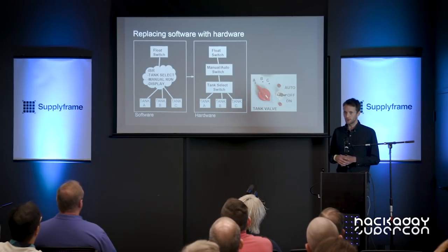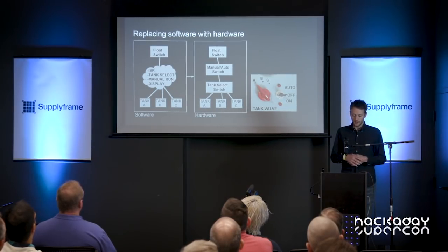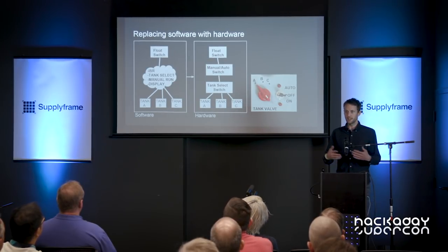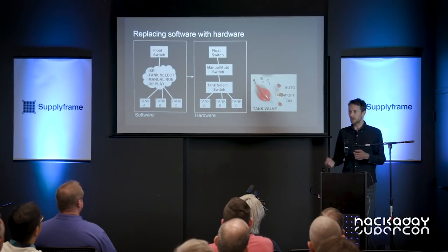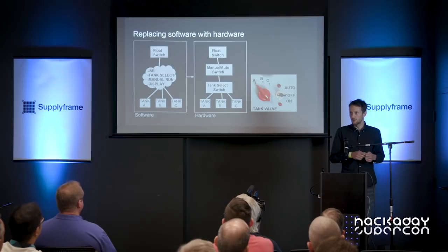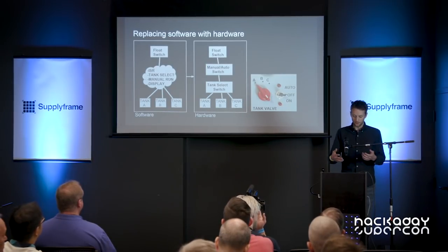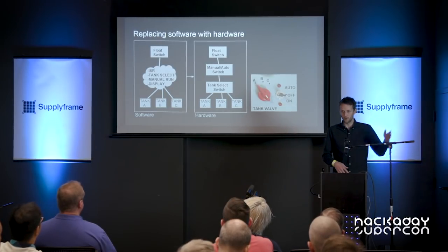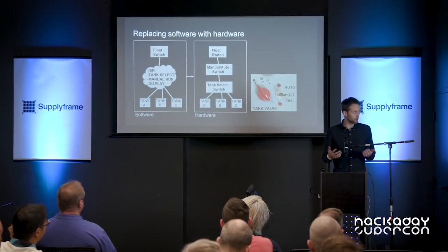So I was contemplating the size of this software at some point because it just didn't quite feel right. And I realized that, first off, this float switch, the way that I'm maintaining the level, the software is basically just routing the value that it reads from the float switch to a pin for whatever selected tank. That's what the ISR is doing. It's basically just acting as a dumb switch all the time. If that one pin is high, it raises the other pin high.